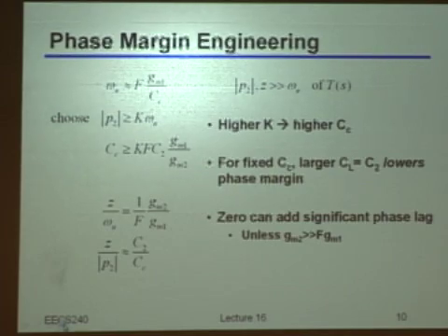So it's not that, as you were taught maybe in 140s, you have to just make sure that your amplifier is unity gain stable. It's not just what we want, because it depends on the feedback. Most probably, in your environment, you know everything that you have to deal with. So basically, you have some settling requirements, most probably. These ones are going to dictate really how much you have to compensate your amplifier and how far you have to go with your phase margin, right?